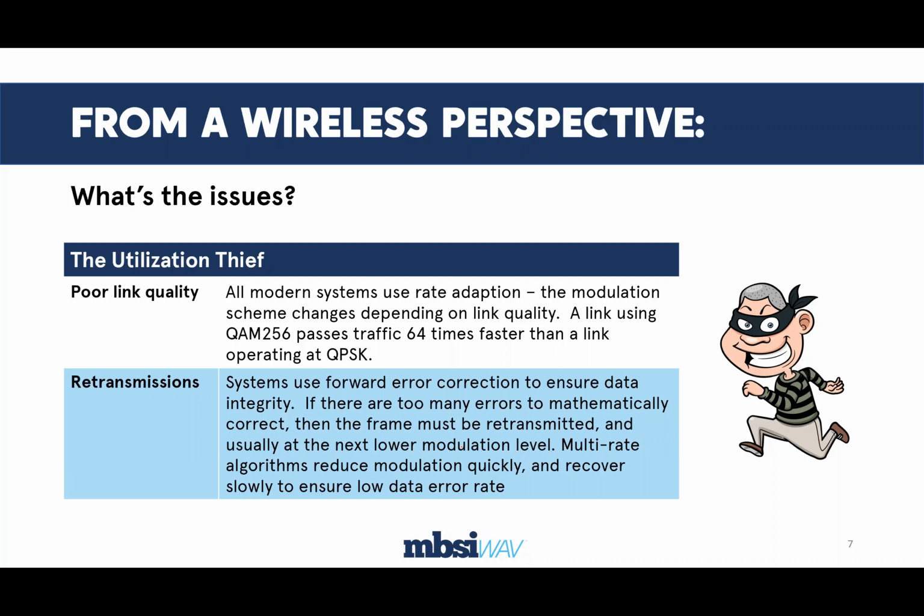Then the access point will lower the modulation level to QAM 64, and it will resend the frame again, taking up more time, but the rate is lower. The bits per second rate is lower over the air, and we end up in the situation where maybe it's successful at QAM 64. The radio will stay at QAM 64 for some time, expecting the errors to come back, and they won't go back up again.